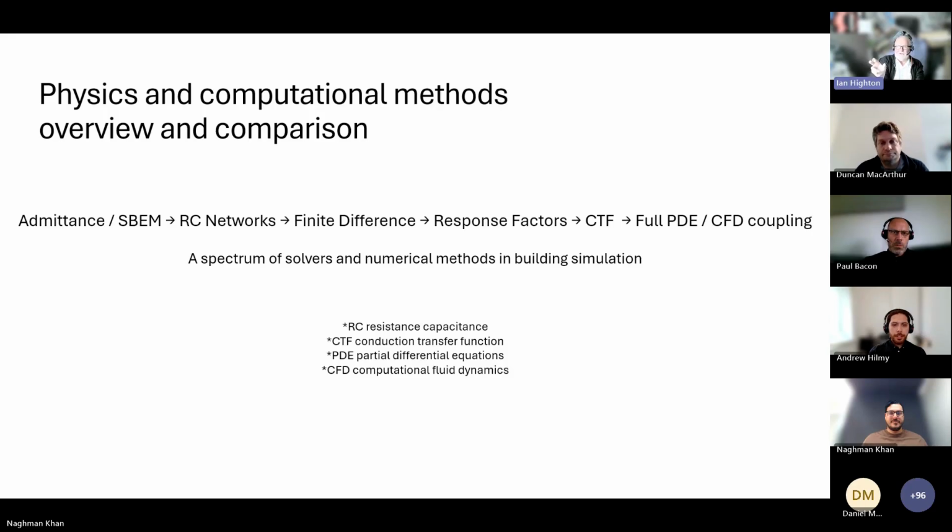So again, I'd say go do the TM33 tests, particularly the conduction tests, and see what you're getting, particularly for lightweight structures. Finite difference will have trouble picking that up in terms of accuracy. And you've also got the speed side of it. You've got to put a lot of nodes in there, and it's not an analytical solution. This is a bit like comparing Newton-Raphson to find the root of a quadratic equation, for example, where you've got to go gradient, go up again, gradient, go up again. There's a lot of computation to get close to the answer, whereas if you've got the quadratic formula, that's about 10 floating point operations and you've got the exact answer.